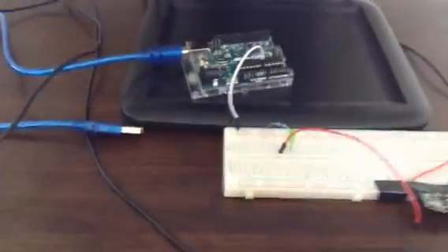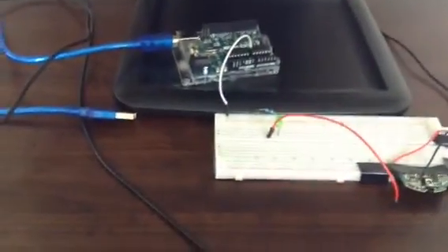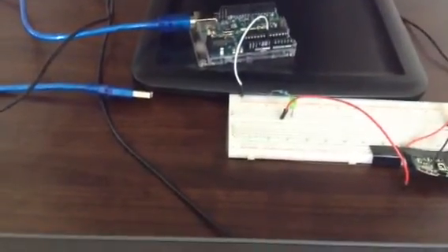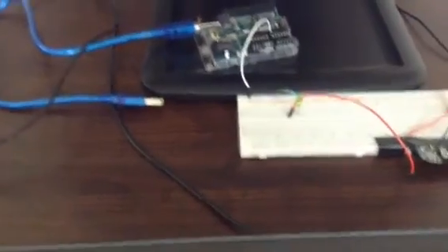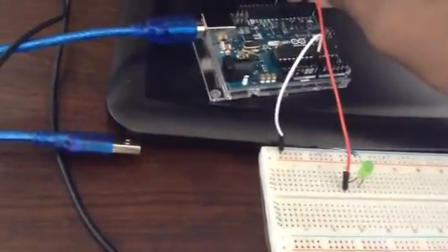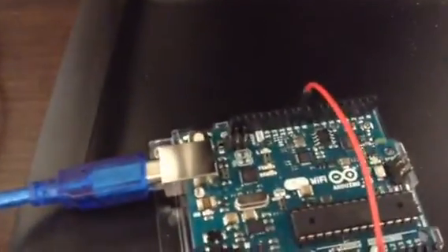And connect this one. Because we want the LED to fade, the LED should be plugged into a special pin called a PWM pin. What a PWM pin does is, instead of just on and off, it's going to adjust its value, like its brightness, which is what we want when we fade it. So you have to connect that to pin 9 like that. Okay, so that's pin 9 if you can't see, but yeah, that's pin 9.